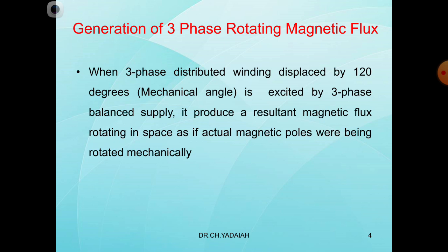During this period, our main rotor magnetic field and stator magnetic field are linked to each other, magnetically coupled, and the rotor rotates in the same direction as the stator field. Now the rotor is under running condition. Now it is ready to take any type of load. These are the principles of operation of the synchronous motor we discussed in the previous class.